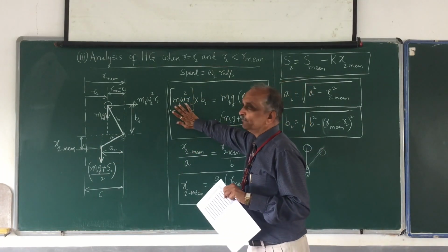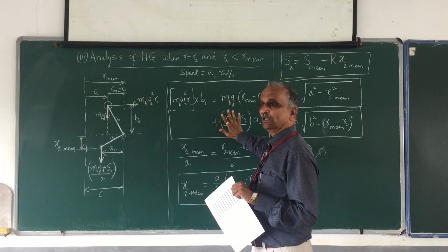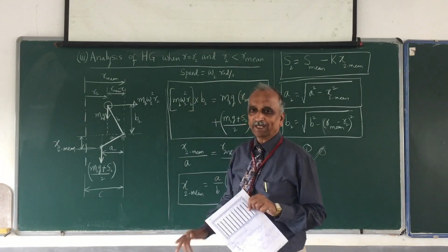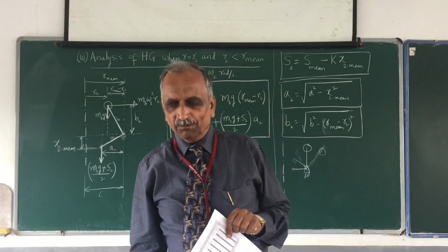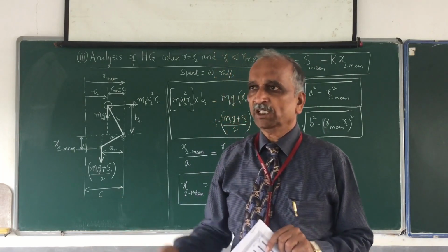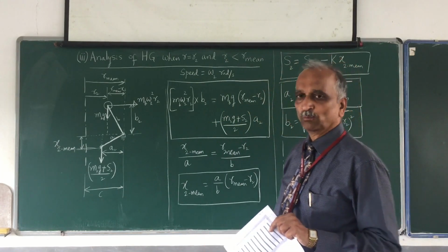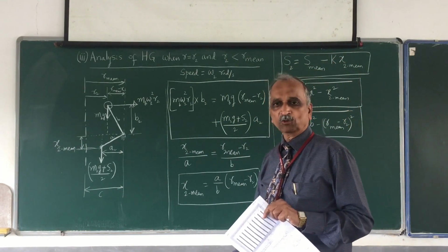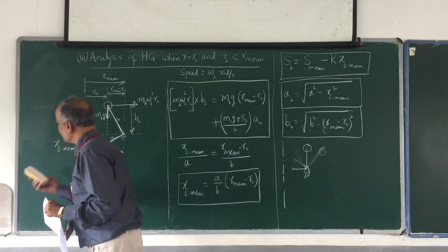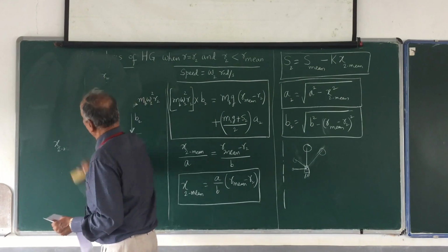It is only the centrifugal force multiplied by B equal to the force at the sleeve multiplied by A. This is what we mean by the obliquity effect. Maybe in one of the problems I shall show both: how the analysis goes if I take the obliquity effect, and what changes if I don't. Okay, now let me take one problem.